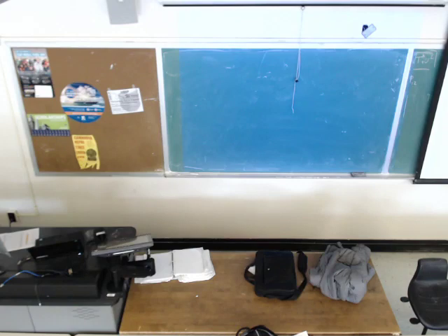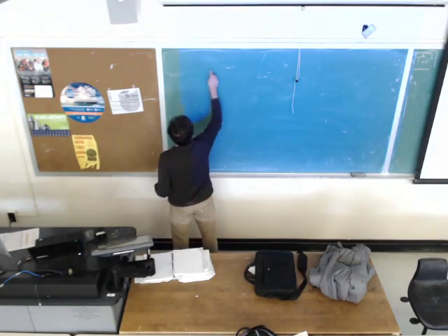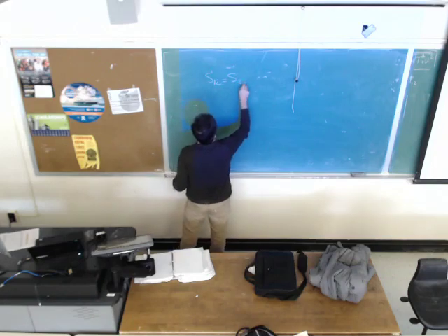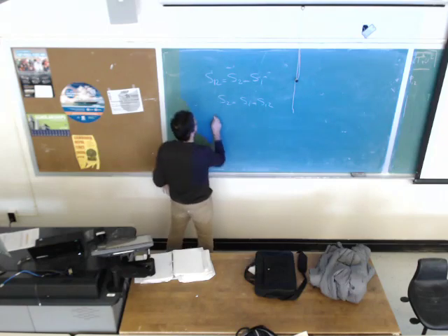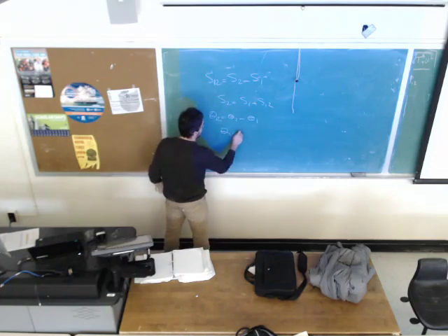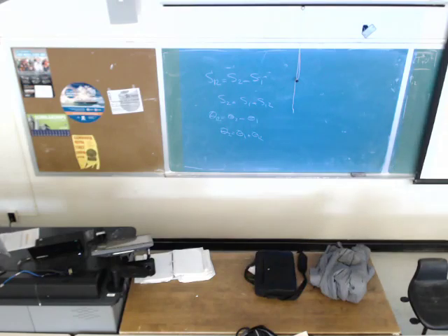Then, same as the four-bar mechanism, we write all equations with respect to the first precision point. So instead of having S2, I replace S2 by S1 plus delta S1, 2, and I replace theta 2 by theta 1 plus delta theta 1, 2, and then we are going to rewrite this equation with respect to the first precision point. I'll finish it tomorrow.